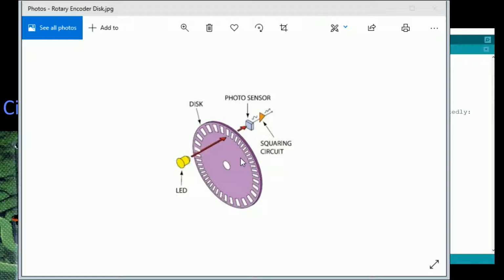What we're doing is we're using a mechanical version of this. Basically there's a bunch of electrical strips on here, and as we turn it, we're going to make and break contacts similar to a potentiometer. So with a potentiometer, we change the resistance as we turn it from its minimum to maximum position. An encoder turns the full 360 degrees, and it makes and breaks a bunch of small contacts mechanically as it moves around.